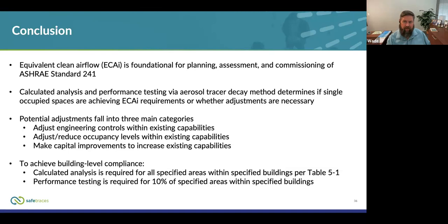Right. And I think some of that is, if there's a method of test, we're using it. For getting CADR, AHAM has a very prescriptive test that you have to follow. Normative appendix A gets into that. So if you don't have that method of test, you can't test.